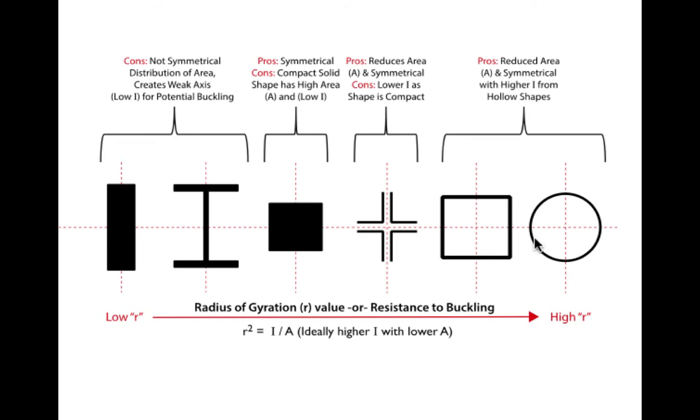Fundamentally, we are looking for rotational symmetry in our column shapes because we have to design for the worst case. In beam design, remember, we're looking at the deepest possible beam in one direction, the section modulus in its best case, because we know which direction the load is coming from, but we don't know which direction a column is likely to buckle in.